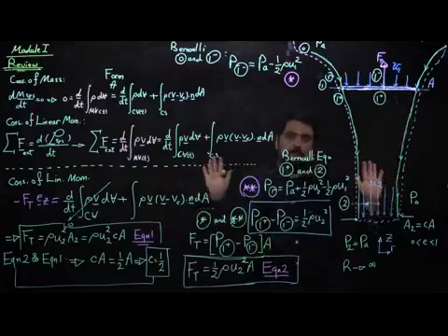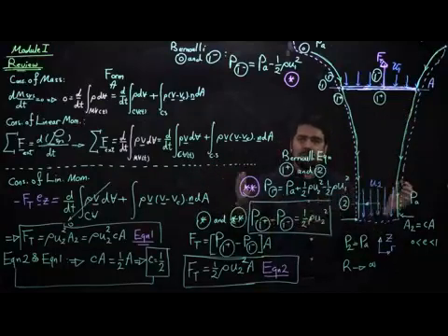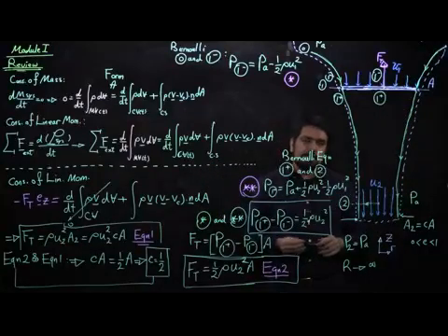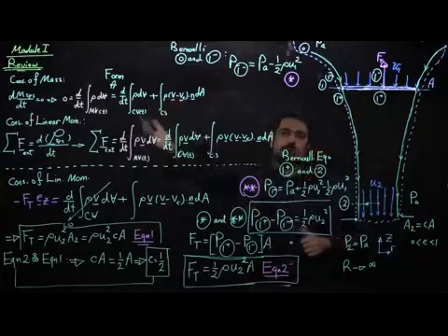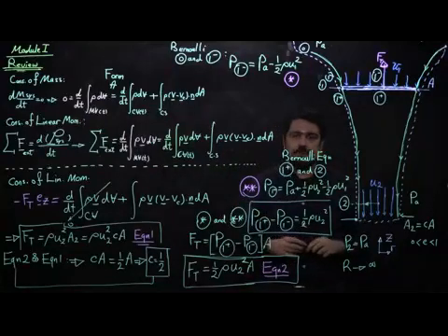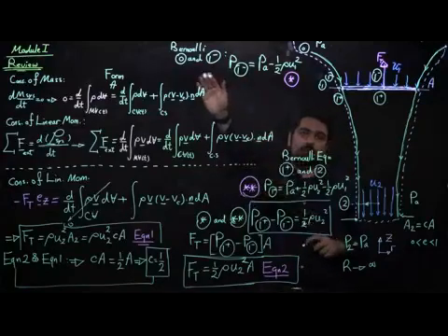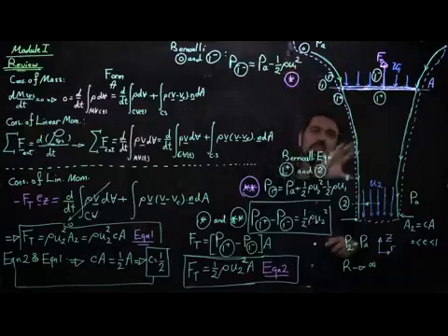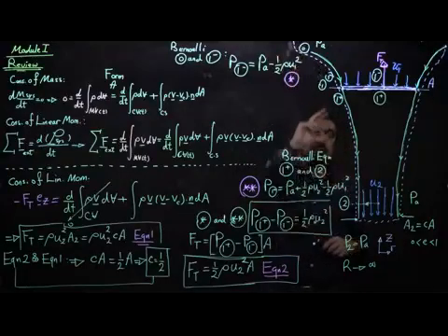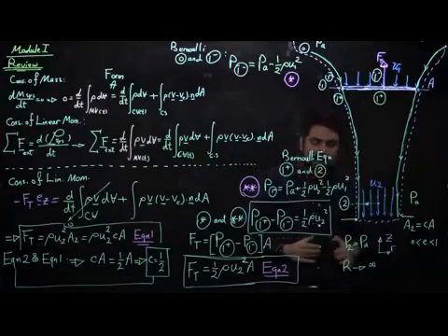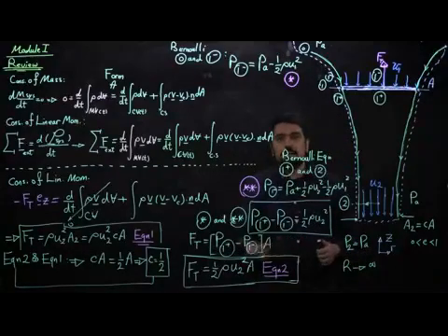I just took a step away, looked at the big picture, the big model of this geometry, flow and phenomenon, and used my understanding of conservation laws for both mass and momentum, and something related to energy which is captured by the Bernoulli equation in regions where it is valid to use, either before or after the blade, not through the blade. And I found something interesting and useful that I can use in my engineering calculations.